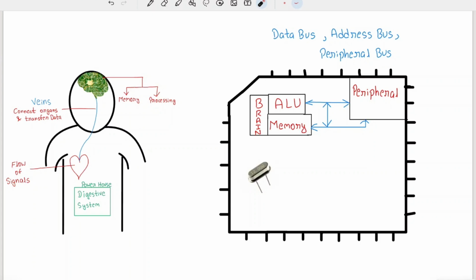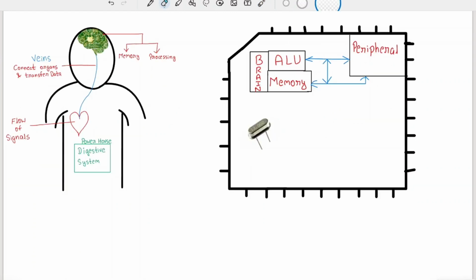The microcontroller is an electronic device, so we need electricity to power it. Generally, microcontrollers use very little power and operate on very low voltages like 3.3 volts or 5 volts DC. This power needs to be given externally to the microcontroller using battery or AC to DC adapter. So this is the basic comparison.